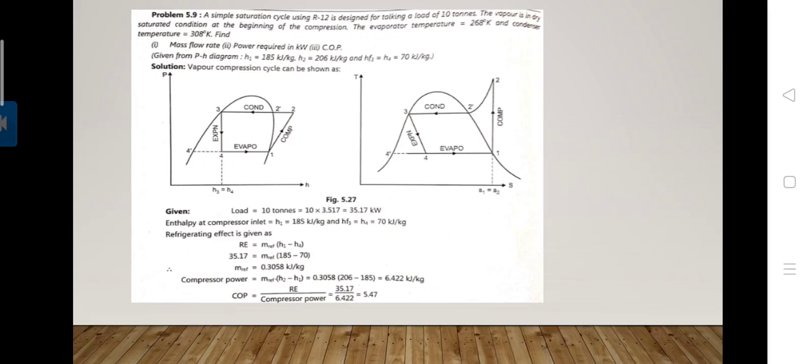In compression cycle, the low pressure vapor in a dry state is drawn from the evaporator during the suction stroke of compressor, and during compression the pressure and temperature increase until the vapor temperature is greater than the temperature of the condenser cooling medium. Next is condensation.